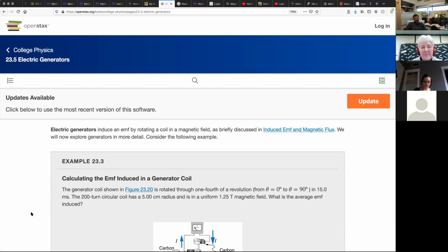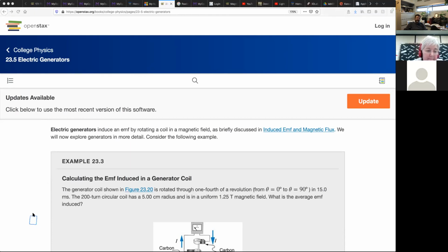Yeah, for the shaking one, what they do is they have a capacitor inside the flashlight that can hold charge, and usually some resistor connected to it. And then they have these coils of wire that are in the handle of the flashlight, many coils of wire. And these coils go up and then back down again here to the capacitor, right? And there's a resistor in there too somewhere. But anyway, as you're shaking this thing, there's a magnet that goes back and forth down through the coils. And that changes the magnetic field through the coils, and it drives a current through here, and it charges up this capacitor. And then when you switch on the flashlight, it connects the capacitor to the bulb. Then you can use it for a little while.